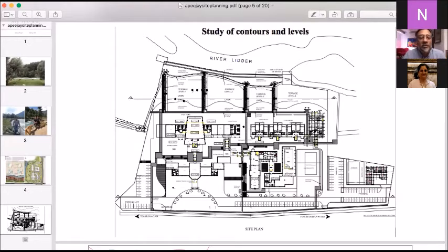Even if it's a gradual site, whenever you handle a large site, if there is water stagnation within the site, it can create a lot of problems. So please look at surface drainage. It is often ignored. A lot of architects feel that it's a plumbing consultant's job to design the surface drainage, but no. In this case, the plumbing consultant came and decided maybe the fall, the size of the canal, the depth of the canal, how much water it would hold, what would be the flow rate. But we had already provided for the canal and these rainwater harvesting systems in our design.